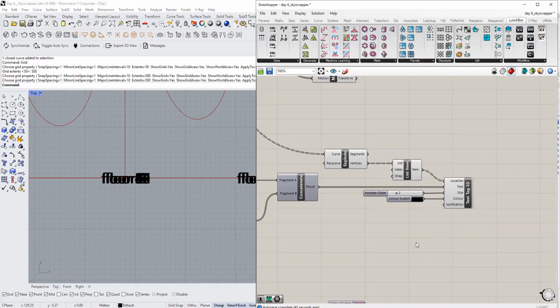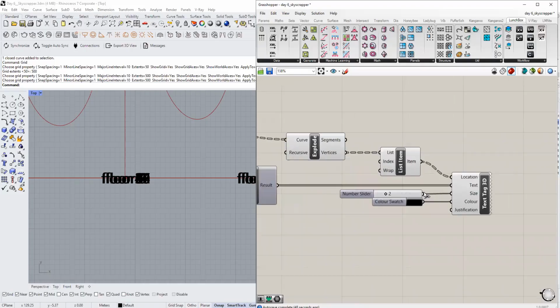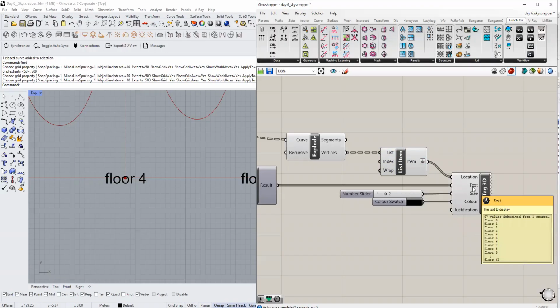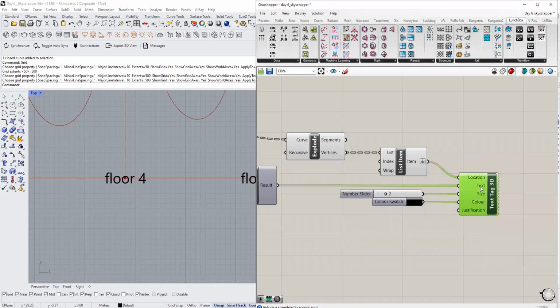Nope. It's again a very common error. We have seen it just a little while ago. Flatten. Exactly, flatten. Look at the inputs. It's a tree and a list. So we just need to flatten it. As soon as I do that, it's rectified. So I have 67 location with 67 ticks. Data matching is proper because both are of same data structure.